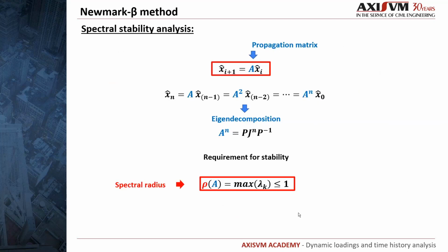As already mentioned, stability is an essential requirement an integration method has to fulfill. The stability depends on the chosen parameters and the time step. Several methods exist to study the stability properties, like the method proposed by von Neumann. This method consists in expanding the solution in a finite Fourier series and checking for growing unstable solutions by analyzing the behavior of the so-called propagation matrix during free vibration of the dynamic system. The propagation matrix is a transformation matrix of the responses between each time step.